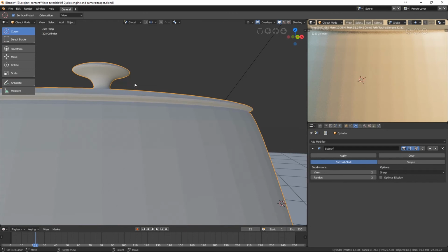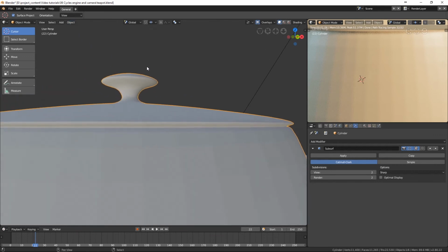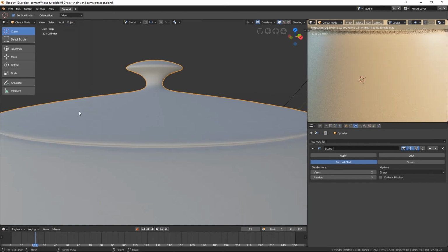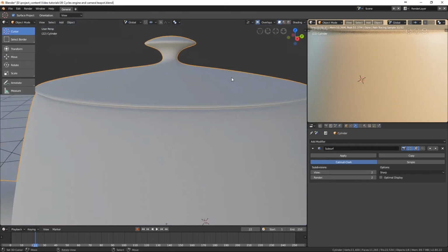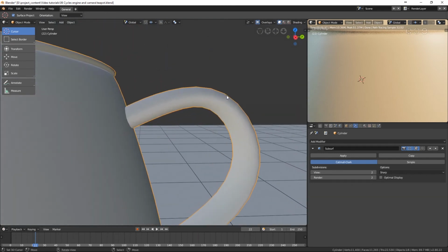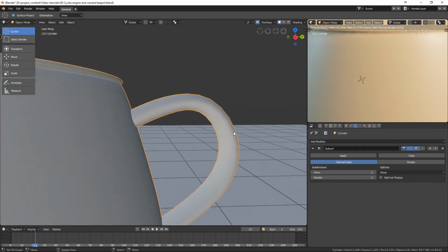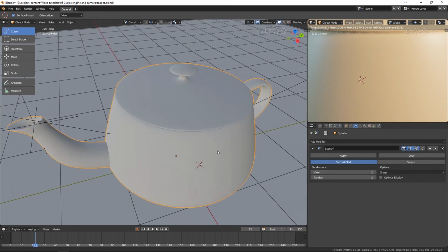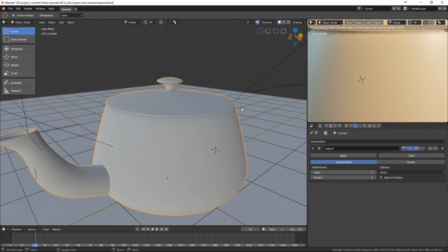And this is actually a cheating technique, and it's not physically correct, but it'll look pretty good. And yeah, select the teapot and go to Object and then Shade Smooth. Okay, so if you look closely, we can see that the edges are still sharp, but the way the computer draws the surface onto the screen, it draws everything as smooth. So that's how you make a smooth surface without making too much geometry and dragging down your computer.